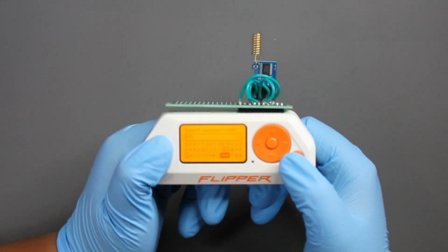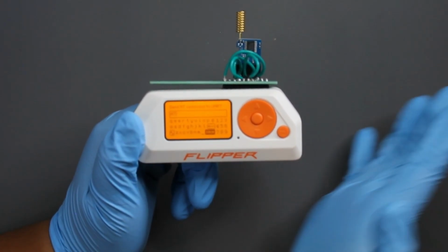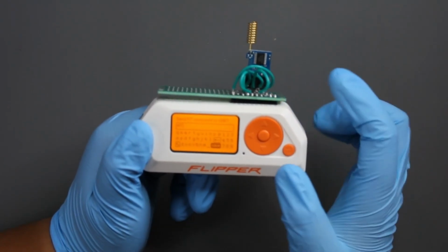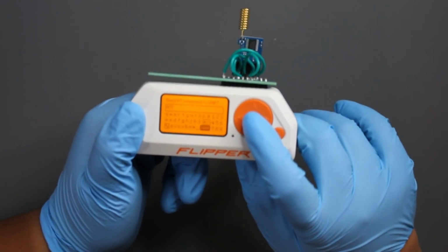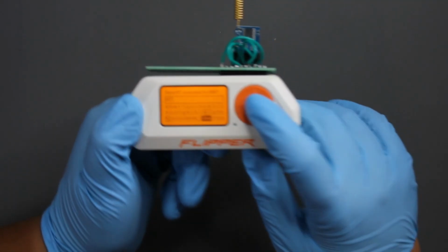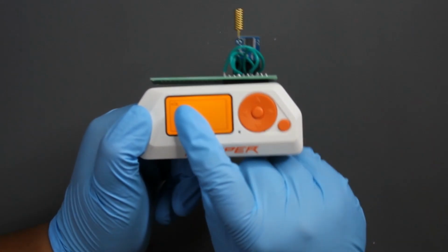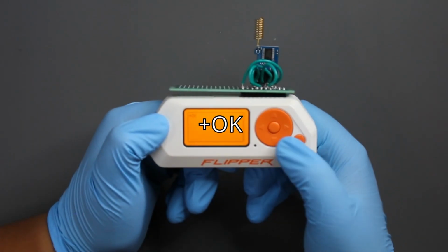go to send AT command. Send AT command is just like the commands that you can use for the LoRa module. And just to make sure that your LoRa module is working and connected, it should say AT right here. Just hit save. I don't know if you can see it. It's a save right here. Just hit save. And if it works, it should say plus OK. Then you should be good.